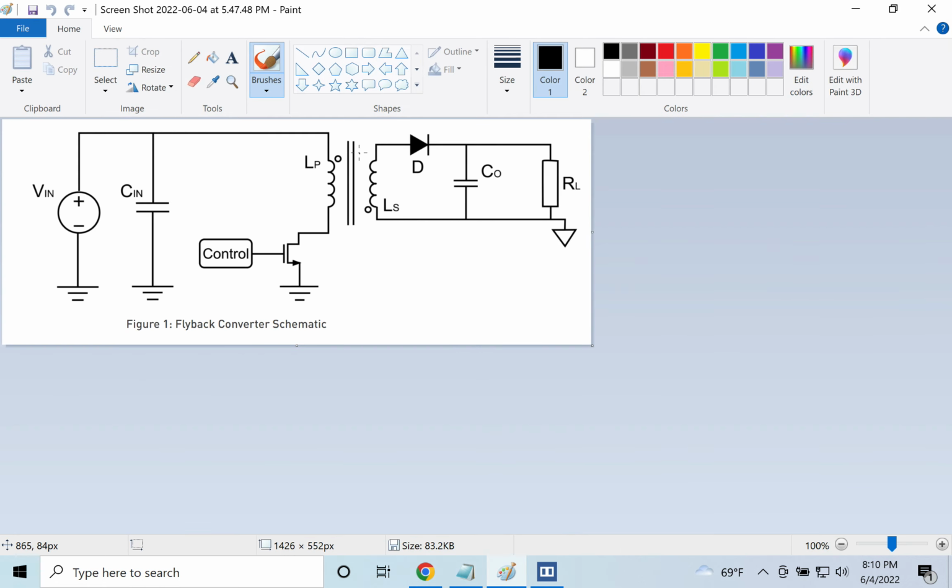So usually in a flyback from primary to secondary, there is a creepage and clearance distance requirement. Creepage is through the PCB, clearance is through the air. So any flyback transformer, any power supply which is plugged into the AC mains needs to handle at least like 3 kV high pot, that's what it's called, or dielectric breakdown, you can say.